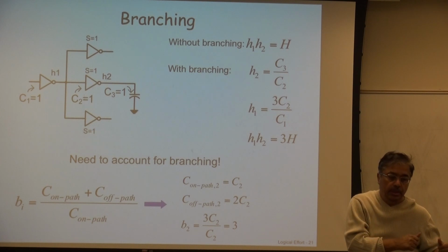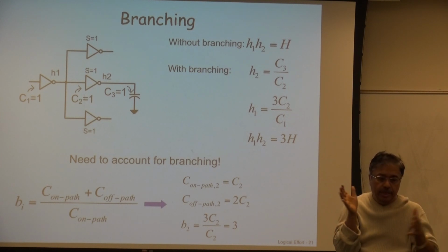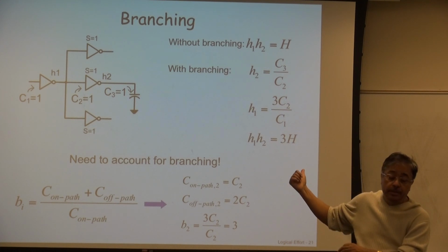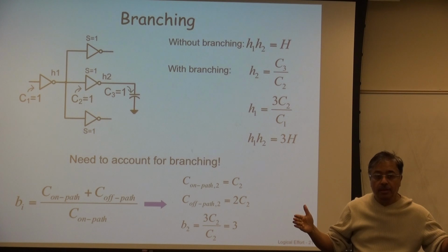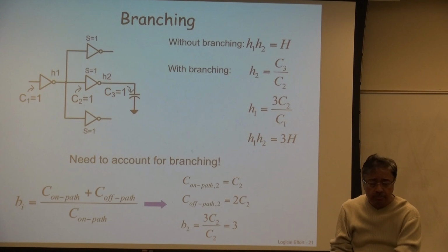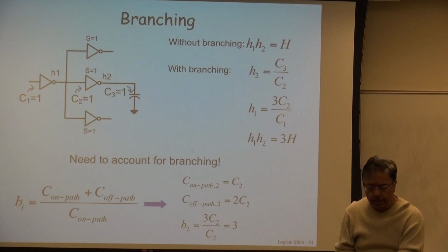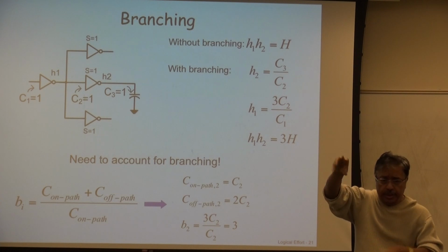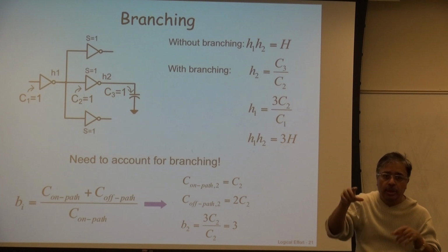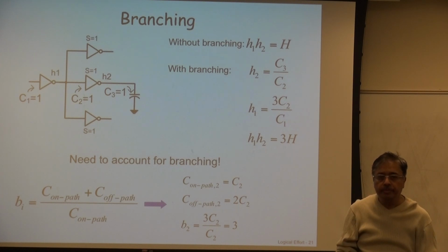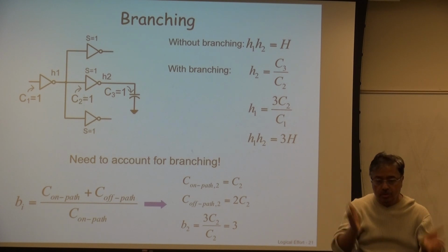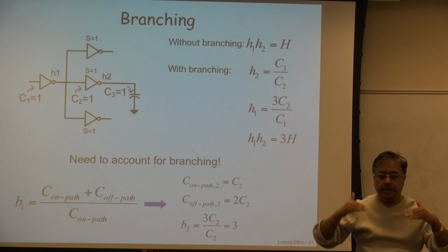So basically, that is what the idea is, that when you're doing the manual design, you're trying to apply this for the critical path, the longest path. So when you do the longest path, unless you know the values of those other gates, their actual capacitances, if you don't know, you can estimate their value and try to optimize this one. But again, this is crude. You'll have to go back to the simulator, you'll have to do all those things, but you do it in the different stages.